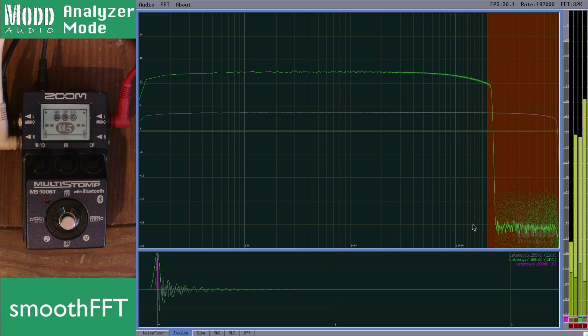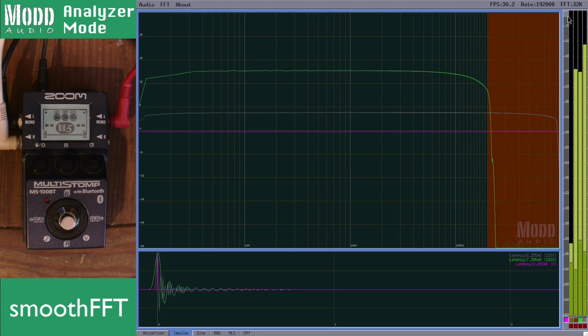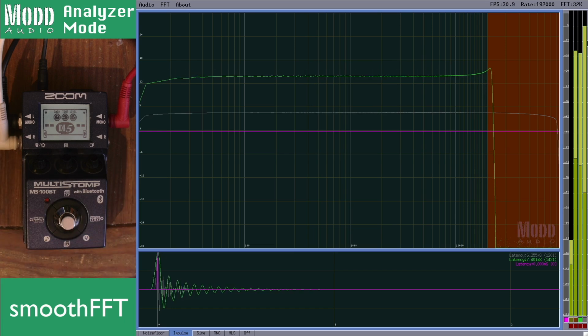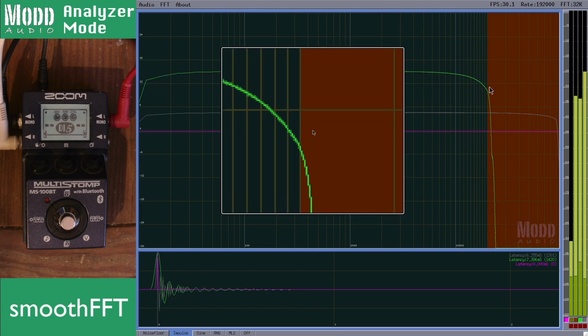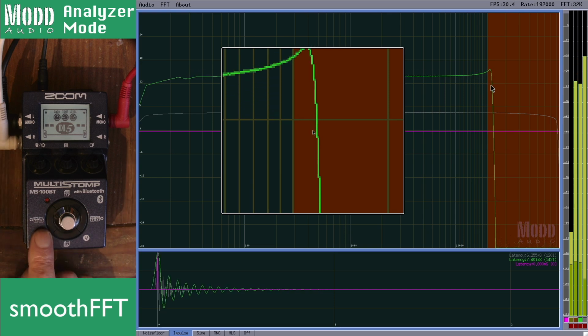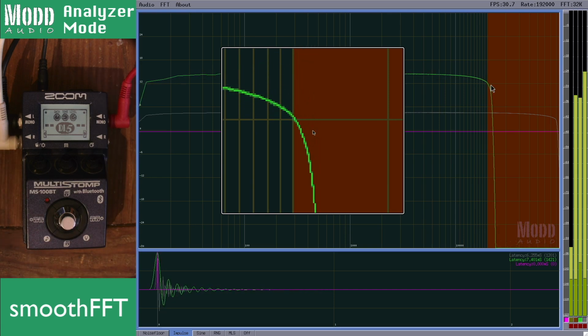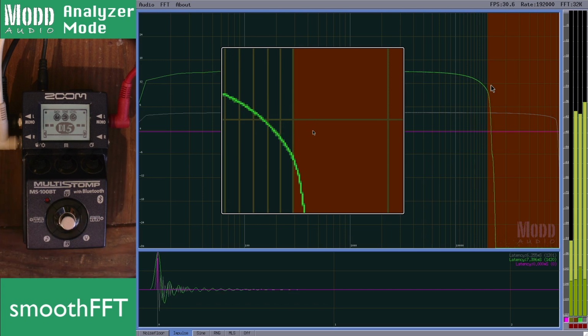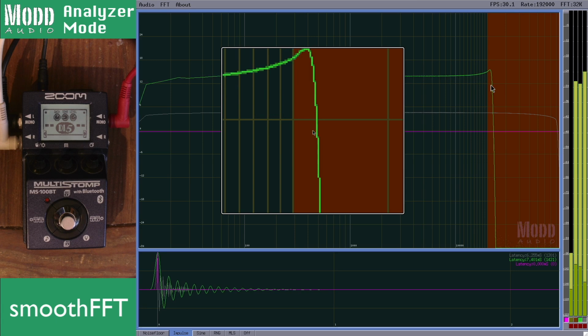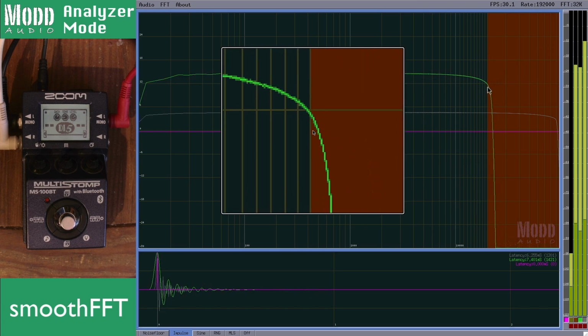But there's some caveats to this. There's not a whole bunch of energy in an impulse response. It's a very quiet signal, so it leads to some weird results. Like you can see this thing go up and down right here. That's basically happening because the sampling rate in this unit does not match the sampling rate of my audio interface. Because they're just slightly off, it's going in between different samples, and you'll see this kind of thing happen.